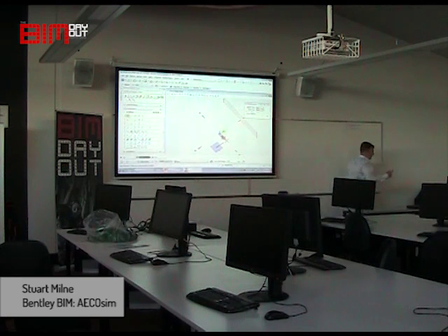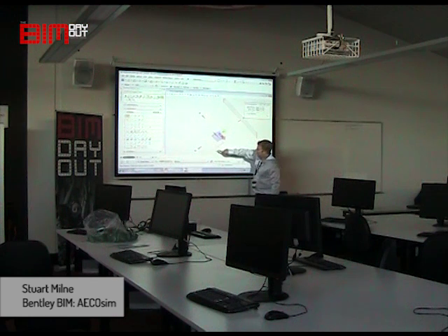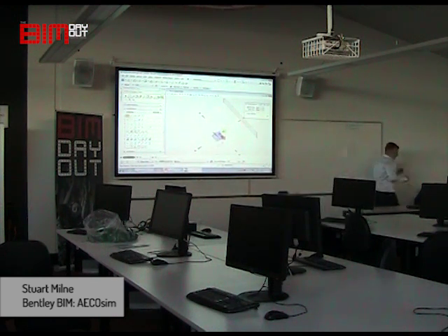What you need to do is click. So you don't hit enter. Everyone kind of falls into the trap of hitting enter. You don't need to do that. It's just 10,000. Click. Then point the mouse in this direction and type in 10,000. Again, click. So what we're going to do is we'll end up drawing a line straight, or a shape. Yeah, we can draw a square, but that's quite challenging.